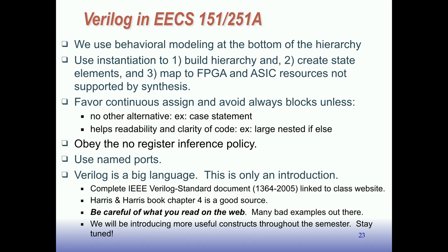Sometimes you need to use instantiation if there are available blocks on the FPGA or in the ASIC that are not supported by logic synthesis. We'll talk more about that later, particularly when it comes to memory blocks. The synthesis tools don't do very well, so we tend to instantiate those.